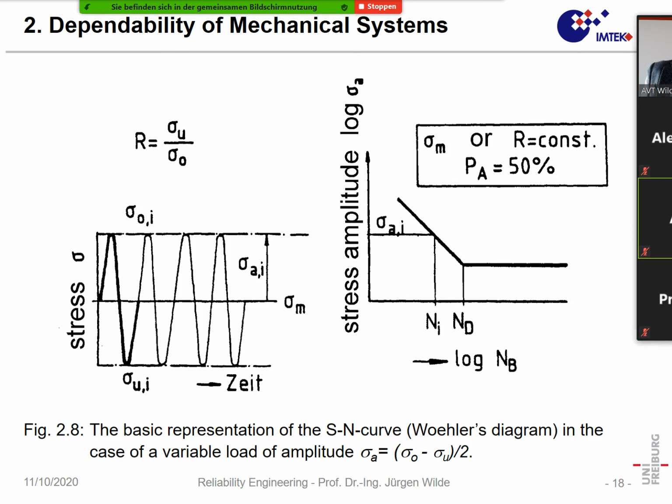So if you look at a crack, normally a crack is opened by stress, but it is closed again by compression, but this closure of the crack will not do any damage. A crack will only propagate when it is under tension or under shear, and that means with a clever superposition of compressive stresses, we can avoid that cracks can propagate.